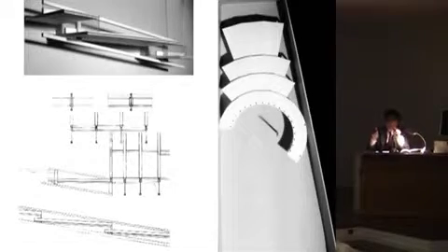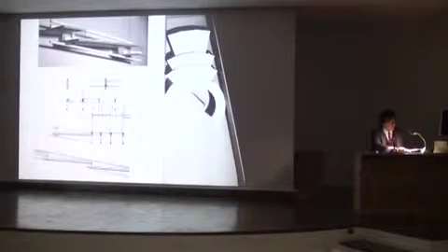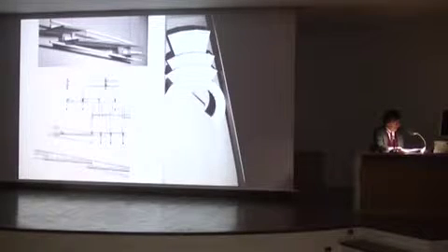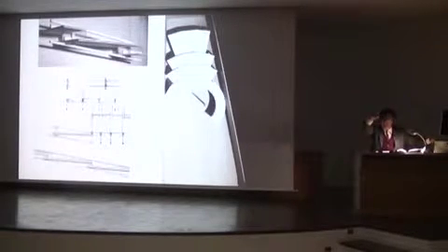Now you can optimize this using small profiles, which at the same time serve another purpose. The cross beam of the windowsill here, of the window shutter here. Let's see, I can't manage to work with this mouse. Here, now, this is an omega profile. Why is it an omega profile? Because the omega profile is so rigid, and it helps in this sense.